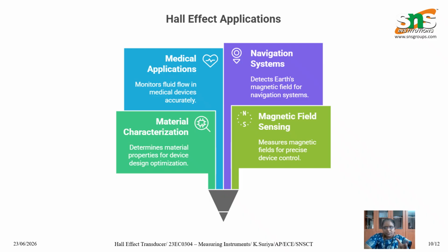In the prototype stage of design thinking, engineers can develop a prototype using a Hall sensor, a magnet, and a microcontroller. The sensor detects changes in the magnetic field strength and converts them into electrical signals. This prototype can be used for speed sensing, position detection, or current measurement applications.